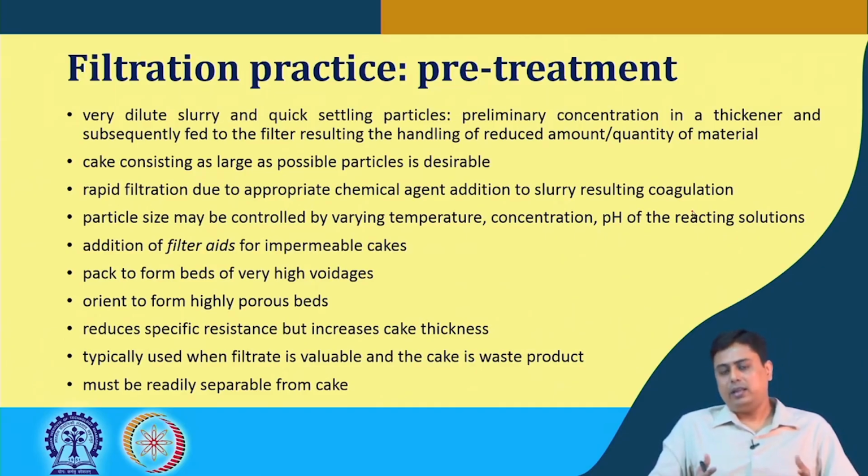Definitely the economical perspective has to be there, how much is economic, but at the same time it has to be taken care that the filter aids are easily separable from the cake, because this is the cake that we are collecting and refining as our valuable product.